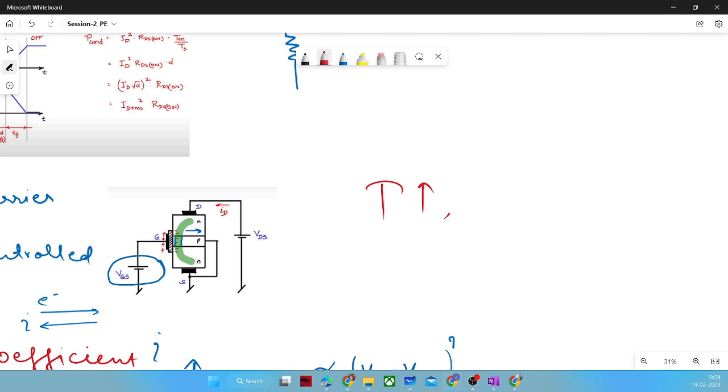Because there are regions where we do not always use IGBTs. IGBTs have several advantages, and the first advantage is they can withstand very high voltage and current levels. So if you are operating high power level devices, then you will have to go for IGBTs. And IGBTs come in between MOSFET and BJT, so thermal runaway will not be as severe in an IGBT.